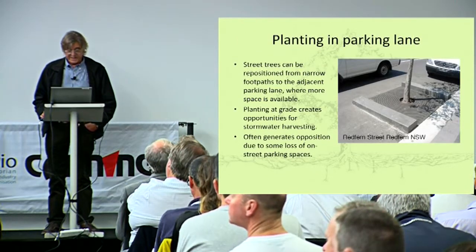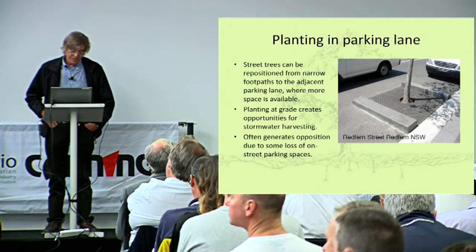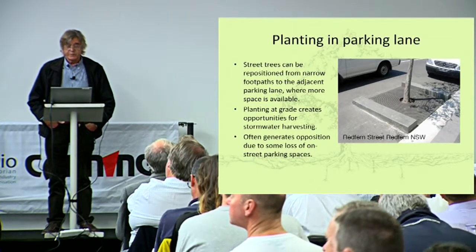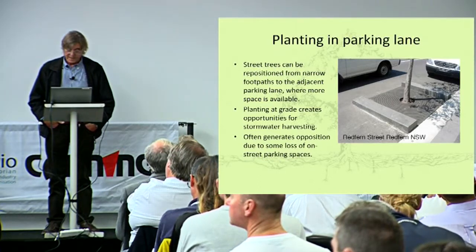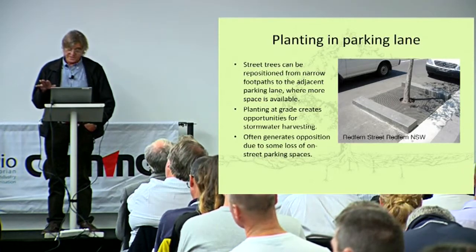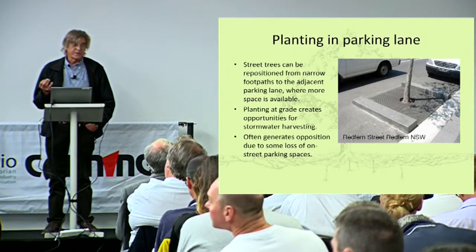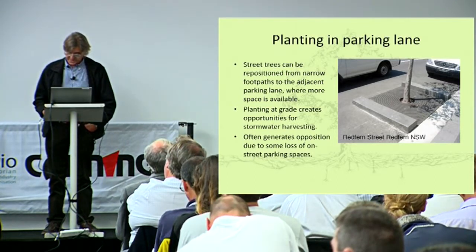So, planting in the parking lane. Parking lanes often offer a lot more space than footpaths for planting trees. If you plant the trees at grade, it's quite easy to redirect stormwater into the tree pit. But often you've got to balance that against loss of parking spaces.